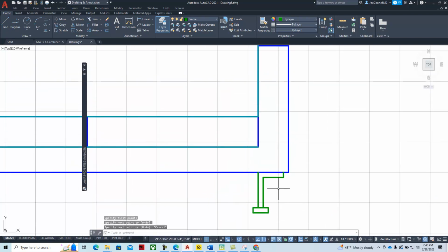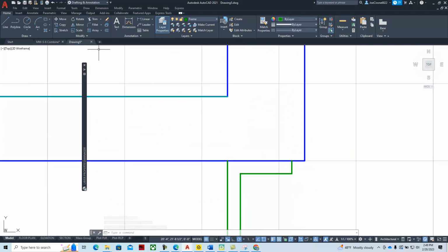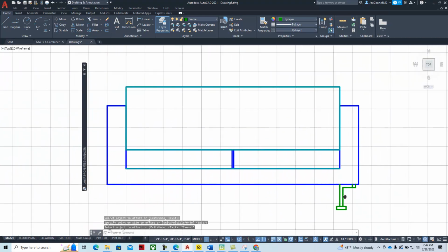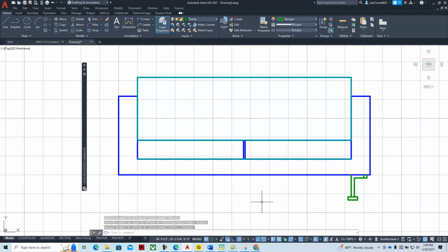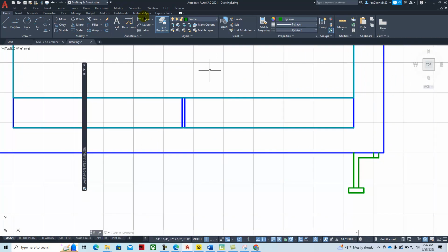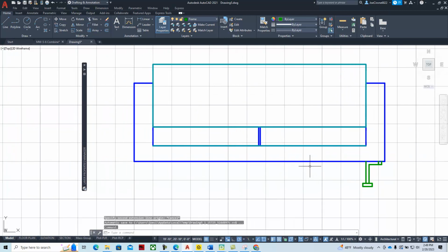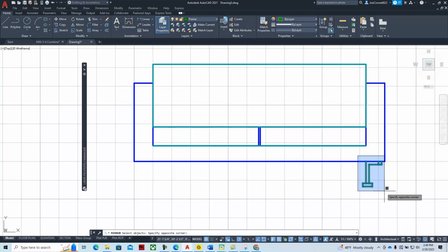And that'll be the geometry for the back of it. And we'll offset this 1 inch. And then we'll mirror this. Do a quick measurement. So that's correct. That's 8 inches. That looks good. We'll mirror the geometry for the frame about the midpoint.